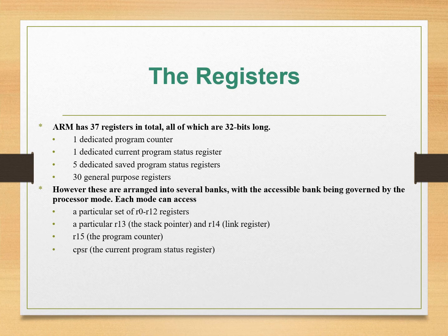As you know, the reason the ARM processor is much faster is because the register is the fastest that can be accessed by the processor. Compared to other kinds of memory, the register is also one kind of memory that is really fast to access. And a privileged mode can also access a particular SPSR, Saved Program Status Register, for each of the operating modes.